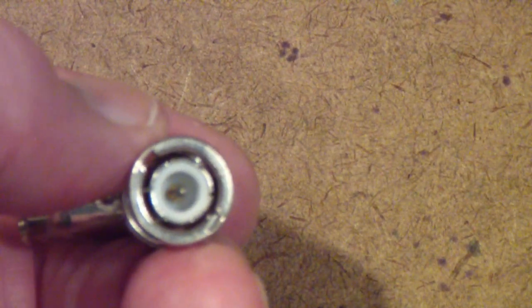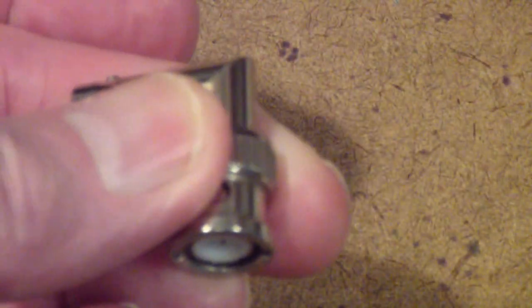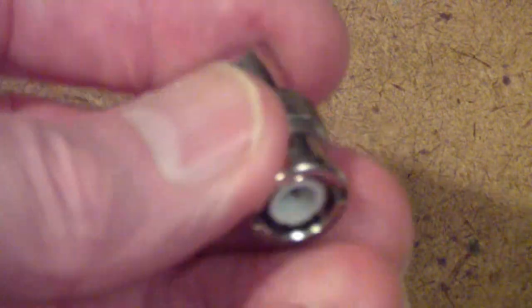This is the male, and generally in connectors, the male or female is denoted by what the most central connection is. In this case, it is a pin. Therefore, this is called a male connector. And on this side, since the center is female, this would be called a female BNC connector. And as you see, it has the little tabs on the side that allow the bayonet to attach when it's rotated. So this is a BNC to BNC adapter.